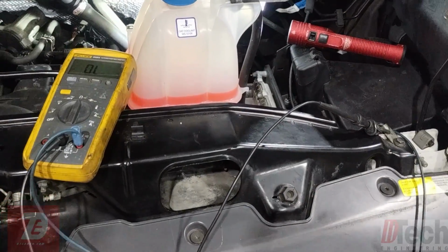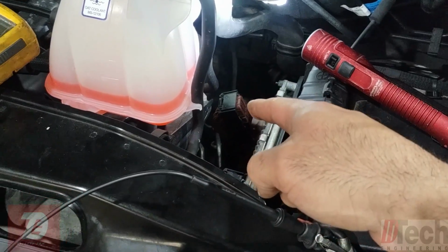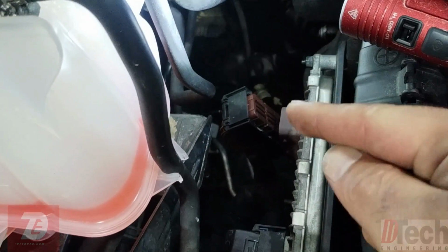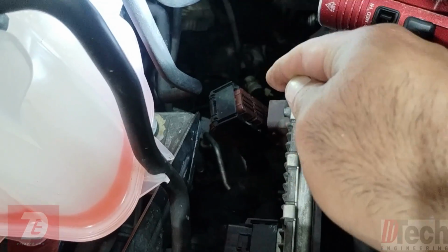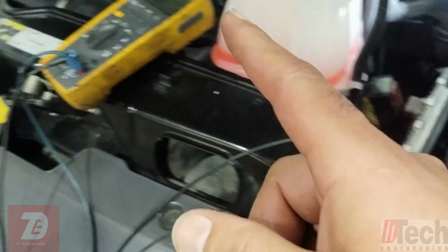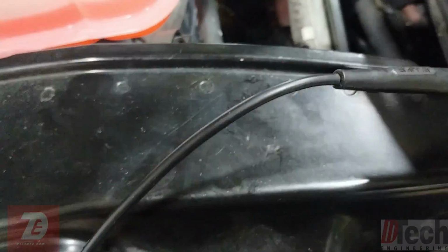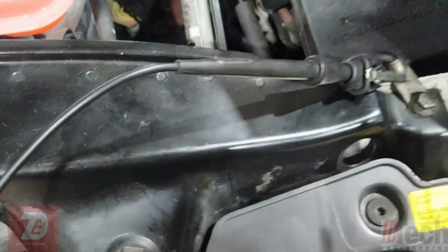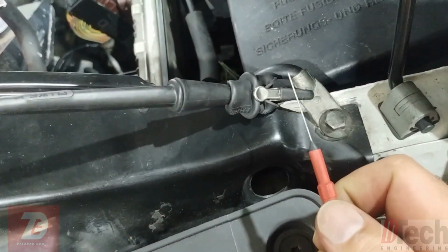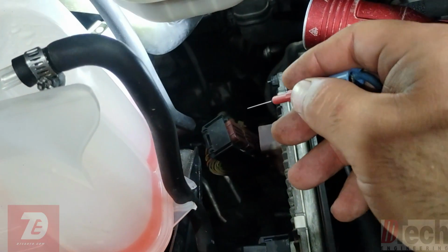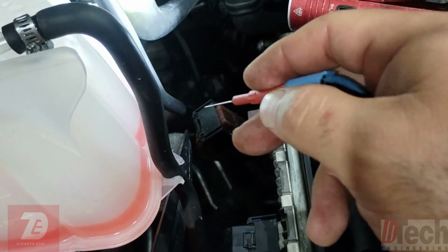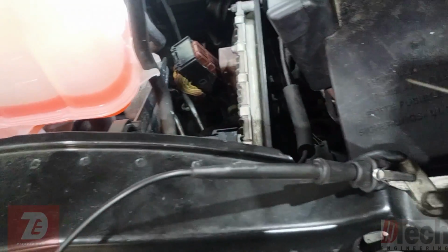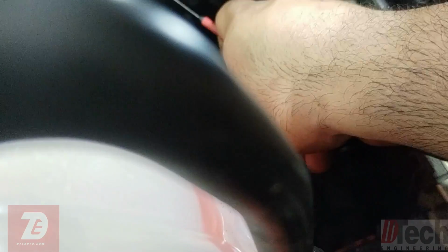Alright, so I've got my computer connector unplugged. As far as the pin, it's the one furthest that way, fourth one in. So I'll show you that. Obviously I've got the meter over on ground, and I've got it to audibly make a noise when continuity is there. So we want to touch that pin, and it should go straight to ground if the circuit is there, and we should hear a beep. So let's see if I can get a good shot of this on camera.